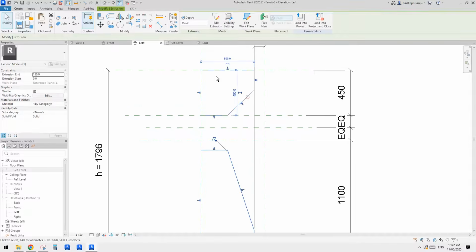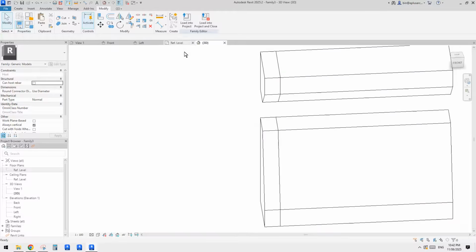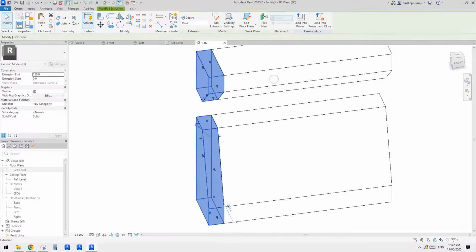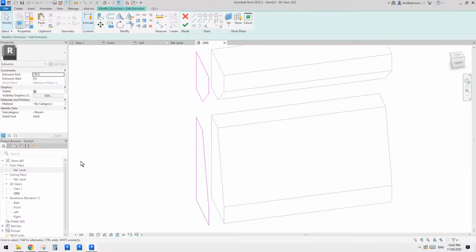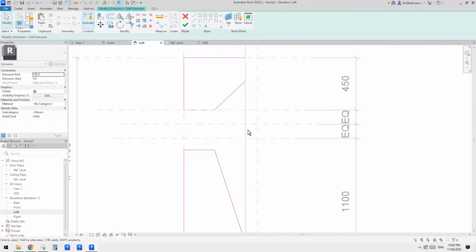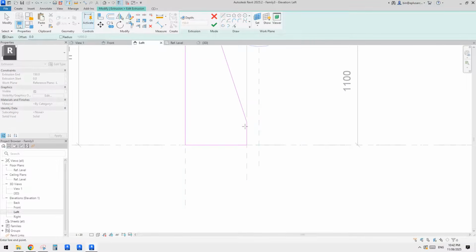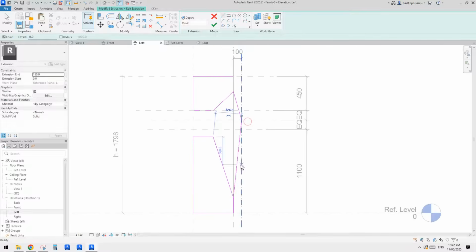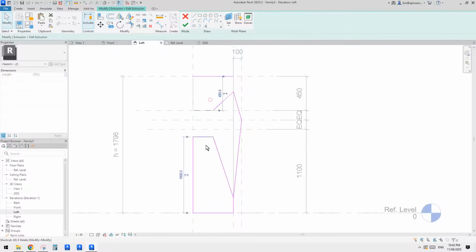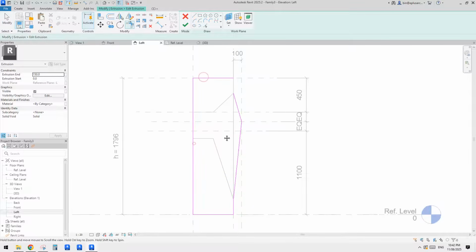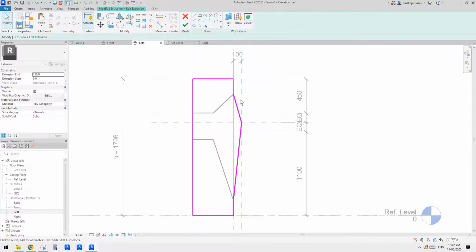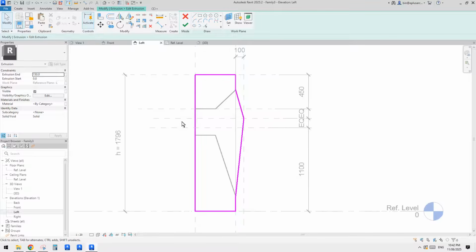And then for this, so I'll just need to go back, make sure I pick the one on the edge, edit extrusion, go back to the floor plan. So I want this one to go from this point out to this one and back to here. And then we can just delete this, delete this, delete this, delete this, and trim TR. So let me just TL, so make the line a little bit thicker. So this will be the edge.